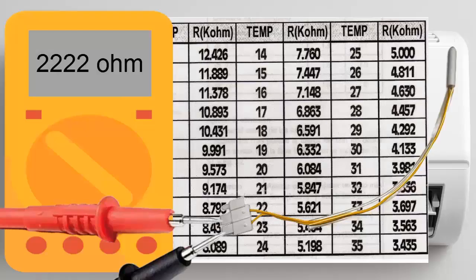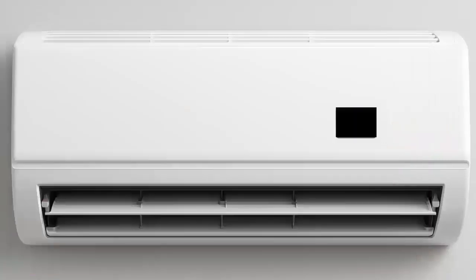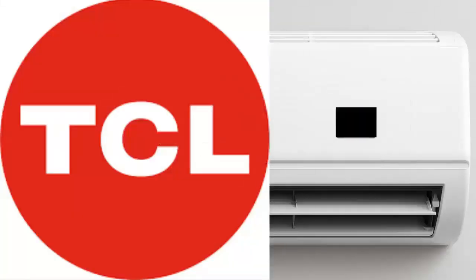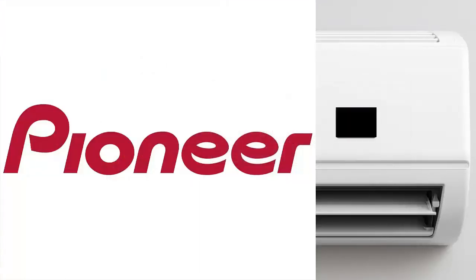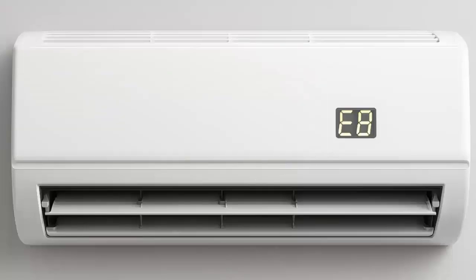C. Sensor out of range. Some units display E8 when there is a fault in the discharge or ambient sensors. The sensor works, but it is miscalibrated. The resistance does not match the actual temperature. Affected brands. Actronair, outdoor discharge sensor failure. TCL, outdoor discharge sensor failure. Pioneer, discharge sensor failure. McQuay Commercial, outdoor ambient temperature sensor failure.